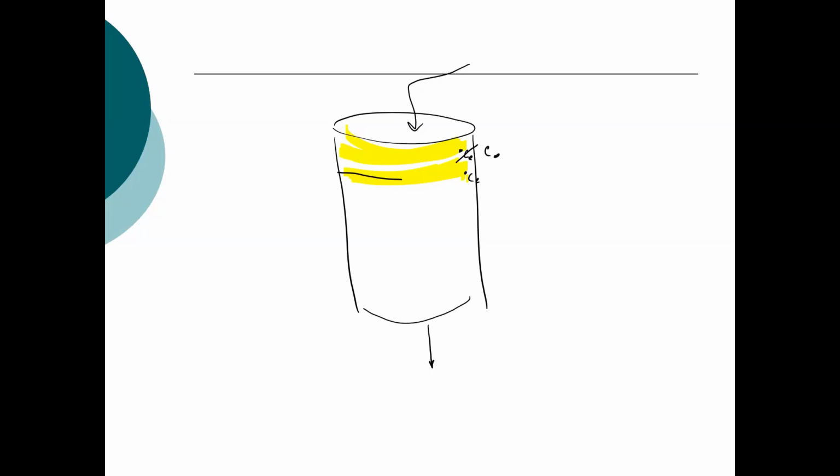I've exhausted, I've used up all the capacity on that resin. And over the next time, that adsorption zone moves down. This here becomes C naught. So I'm not getting any more removal, and this becomes C, the equilibrium concentration. And eventually, if you let it continue, this becomes C sub B. So if I monitor volume through the column versus concentration, it's essentially zero. It begins to increase, and eventually it'll reach C naught, because eventually I've used up all the column.